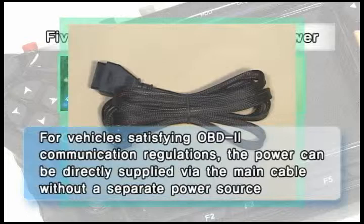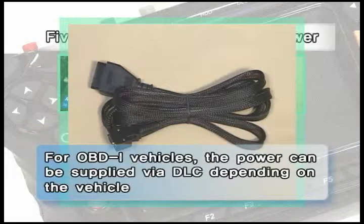The third way is by using a DLC main cable, OBD2 communication. For vehicles satisfying the regulations, power can be supplied directly with the main cable alone without a separate power source. For OBD1 vehicles, depending on the vehicle, power can be supplied via the DLC.